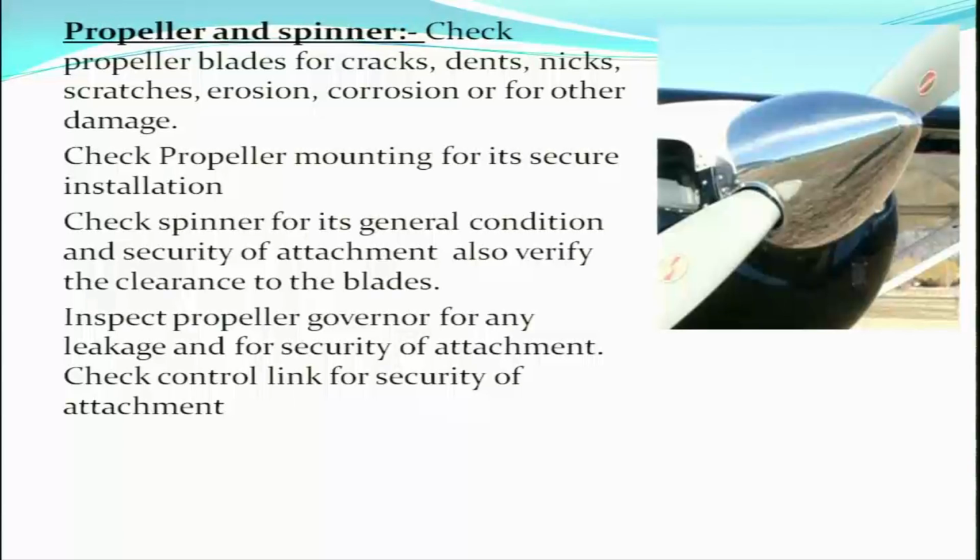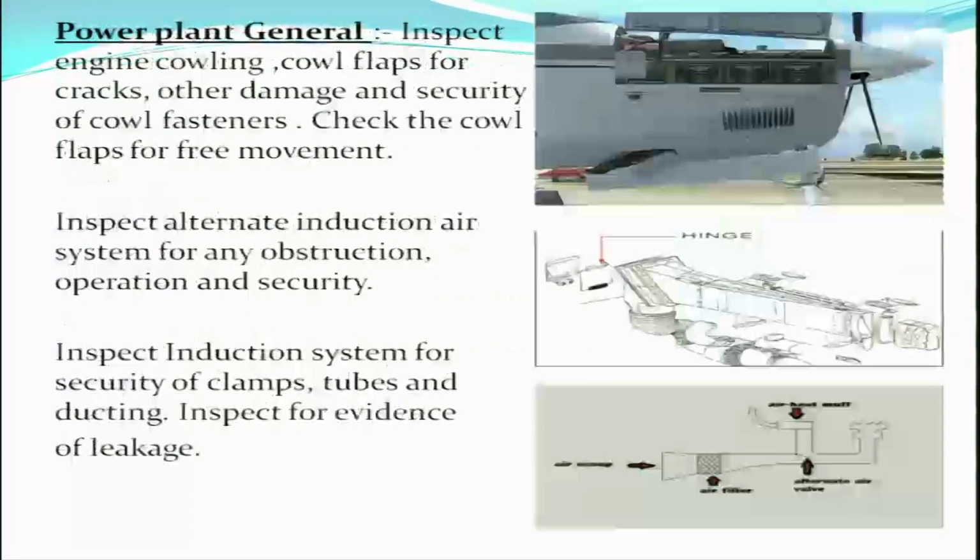Inspect the propeller governor for any leakage and for security of attachment. The propeller governor has to be inspected for any leakage and for security of attachment. Check the control link for security of attachment. The control link is also to be checked for security of attachment.